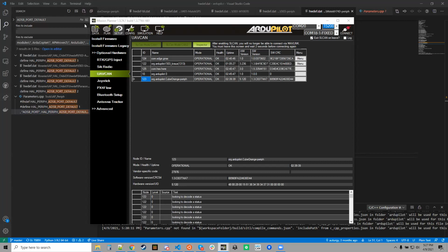We do recommend at least having 256K of flash for a peripheral node. We do have some nodes that are 128K, but it's quite tight, because you basically have two CAN stacks you've got to include. One is the bootloader and the other is the main firmware. And for reliable update, you really need two copies of that stack. That limits it; you can't really go down to very small flash size devices.